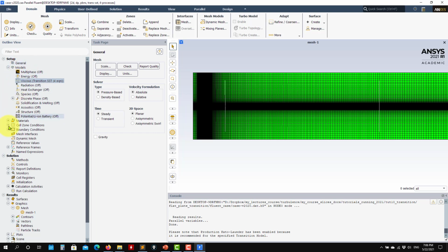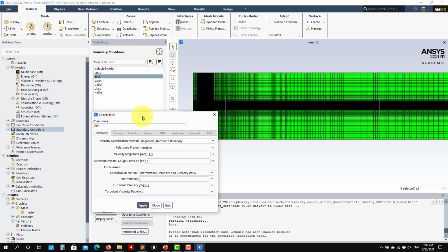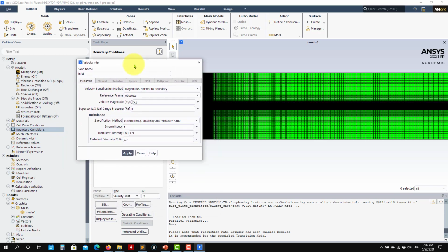Now we go. The other thing that I need to mention is here you got boundary conditions. Again, remember that you have a turbulence model. You need to give boundary and initial conditions. So here there is a new initial condition and boundary condition, which is for the intermittency. Okay, so it's that variable that is going to define where you have laminar flow or turbulent flow. Okay, so here you have it. It is bounded between 0 and 1, and it is recommended to initialize and, at the inlet, to put it to 1. Okay, it might seem a little bit counterintuitive, but this is standard practice. Okay, so put it to 1.